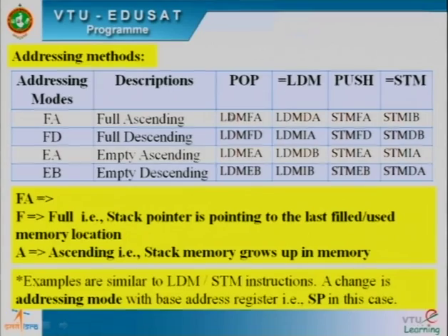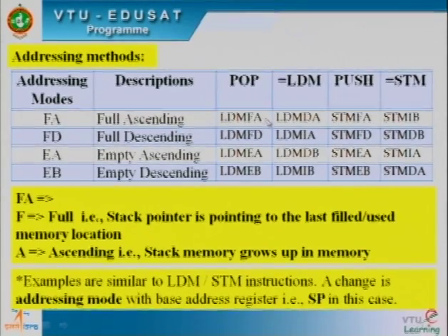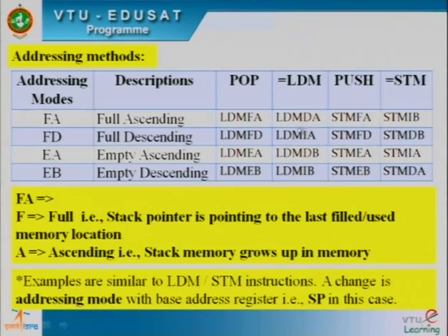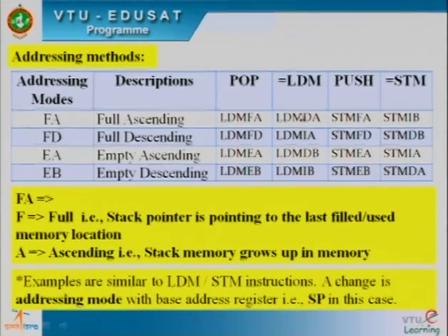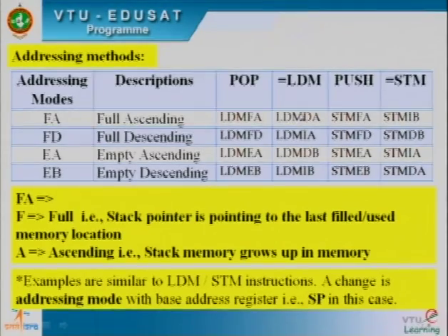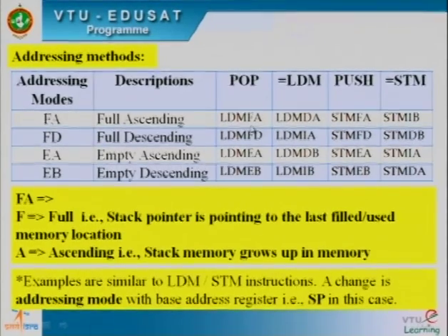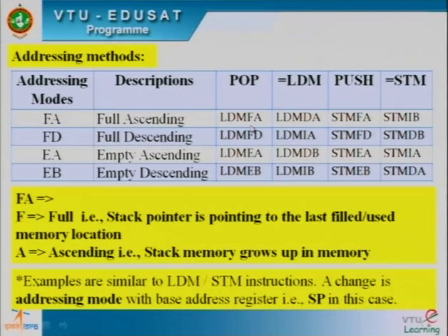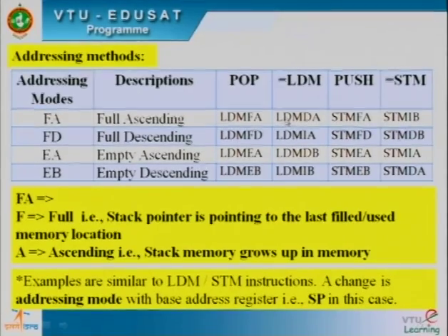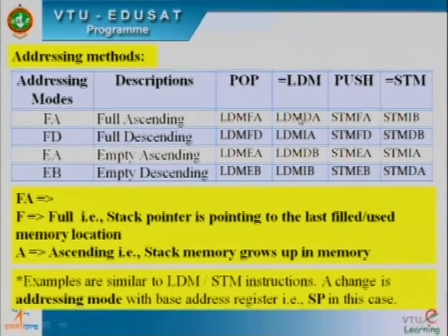This instruction LDM FA is very similar to the instruction LDM DA. What do you mean by LDM DA? Load multiple register decrement after. This instruction we have discussed with an example in the previous slides. So the pop instruction says LDM FA. The LDM FA instruction internally works with the help of LDM DA.